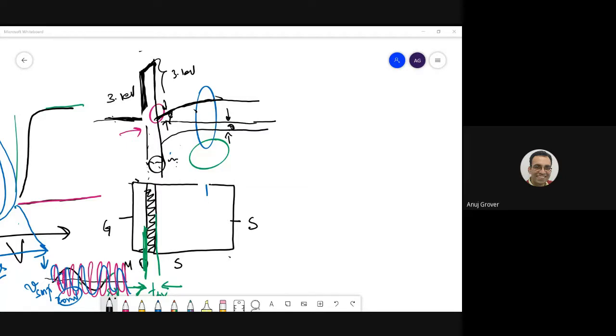Look at it like this. There are so many other things which are already varying in any electronic circuit. Threshold voltage is variable. There are other variations because of length and etching and so many things. As a designer, you do not want to add additional sources of variation which are not in your control. So you would usually want to bias your circuit at one place and then design there.